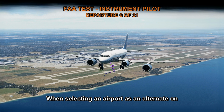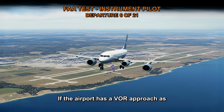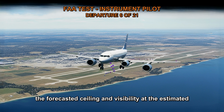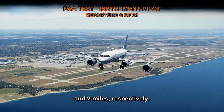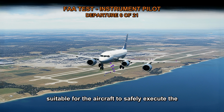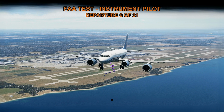When selecting an airport as an alternate on an IFR flight plan, certain weather minimums must be met. If the airport has a VOR approach as the only published approach procedure, the minimums for the forecasted ceiling and visibility at the estimated time of arrival, ETA, should be 800 feet and 2 miles, respectively. These minimums ensure that the weather conditions are suitable for the aircraft to safely execute the approach and landing at the alternate airport.